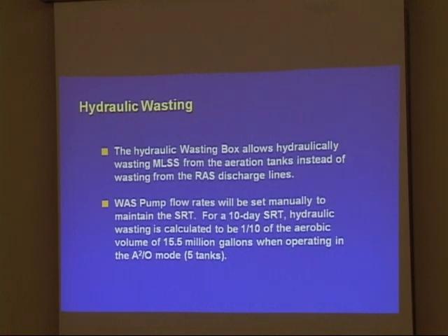Okay, you guys have a hydraulic wasting box, and this is really cool because these hydraulic wasting boxes on each battery allow you to hydraulically waste mixed liquor suspended solids instead of wasting from the RAS discharge lines, okay? And what you'll do is you set the WAS pump flow rates manually to maintain the SRT.